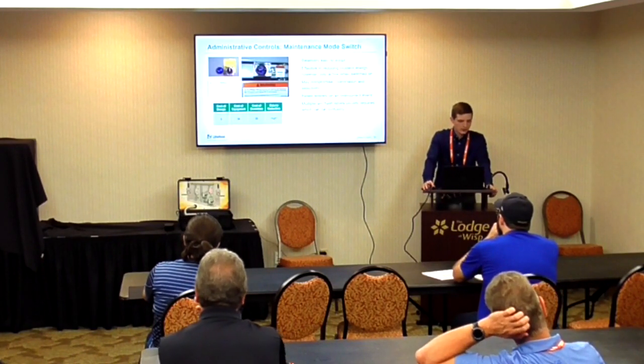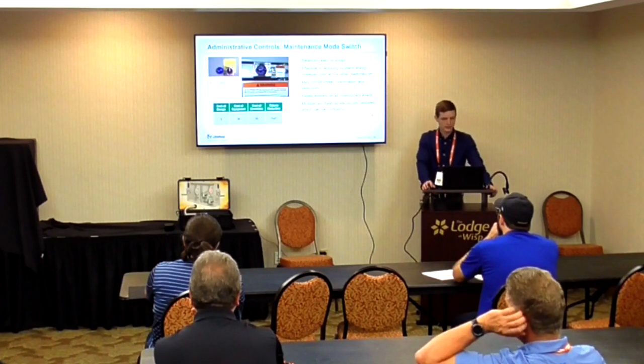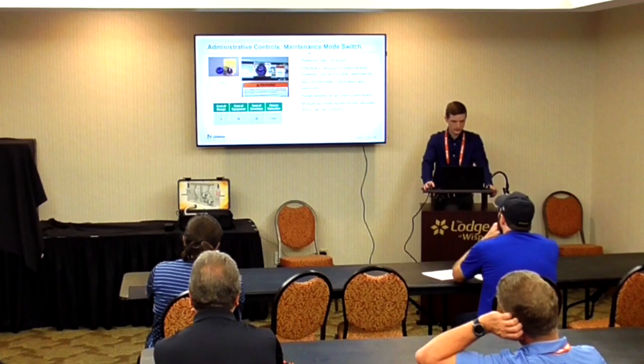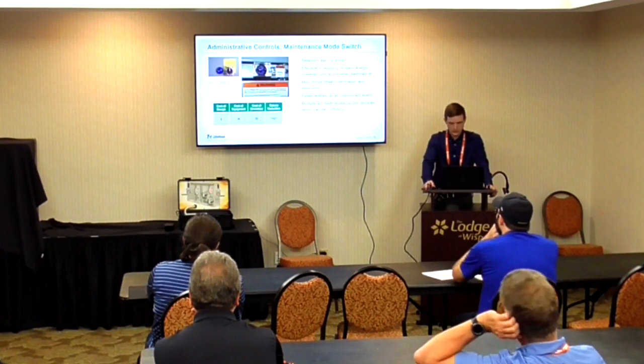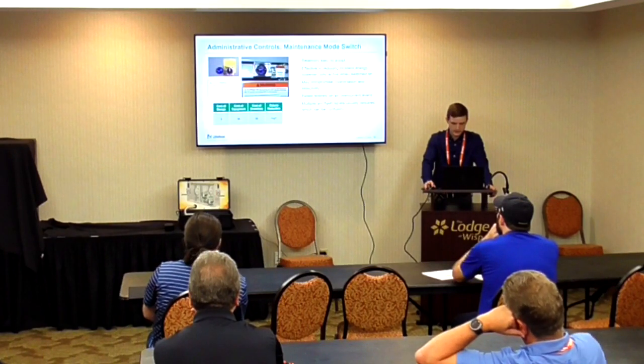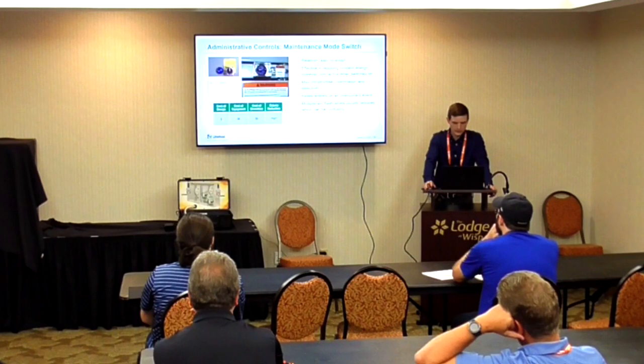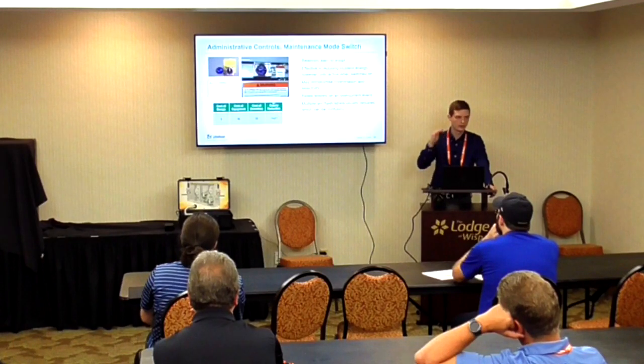Moving on down to administrative controls. We are now on the bottom half of that hierarchy of controls. It's something referred to as a maintenance mode switch or a maintenance mode breaker. It is approved by 240.87 for the NEC, but essentially it's a switch that you need to place into the maintenance mode before you go in to start working on the panel. So this is watching for any overcurrent that goes above what your set value should be.